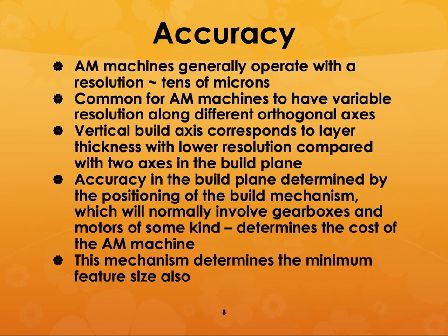Additive manufacturing can have variable resolution along different axes. So in the X and Y planes, it might be better, but in the Z plane, it could be pretty bad. In fact, there will be a lot of ridges that you can observe, and it is not a good thing to have. But sometimes, what you will have to do is hand finish it or do final machining and final grinding in order to get the final surface finish.